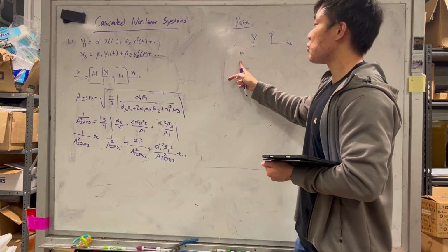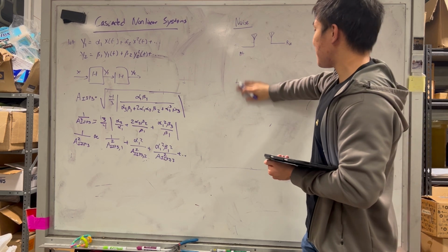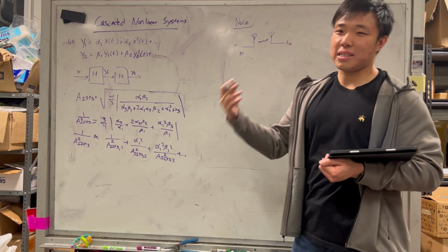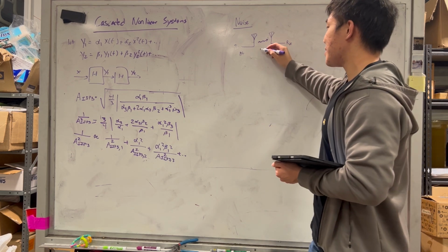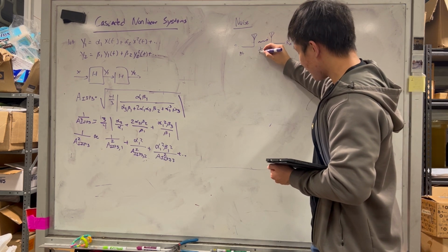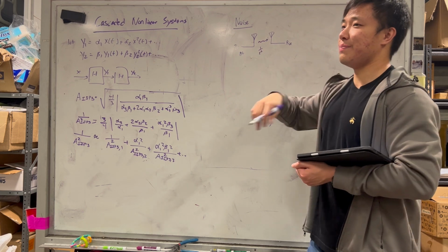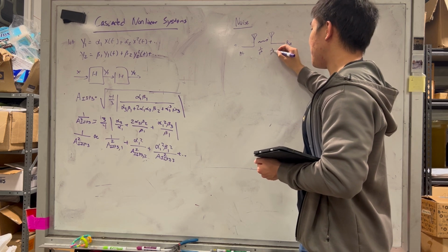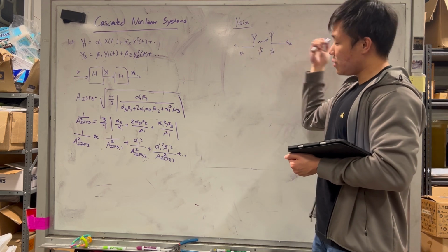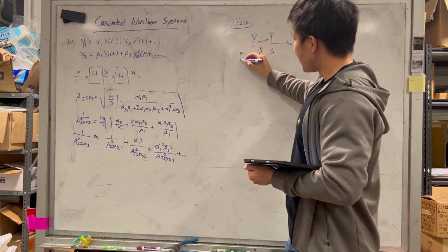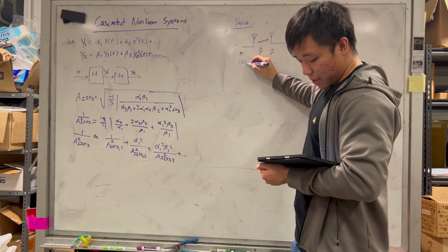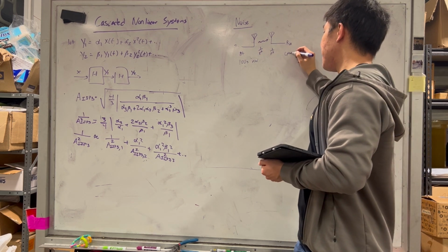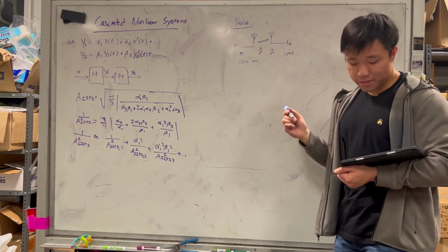And linearity is super, super critical because as it travels through this medium, in classes you'll learn that it gets attenuated by a term of 1 over r squared. But in reality, because of all the interferences of it bouncing everywhere, it's actually closer to 1 over r to the 4th. So you're actually seeing a huge amount of attenuation here. The power amplifier can maybe output something like hundreds of milliwatts. Once you get to here, you're looking at the regime of microwatts. You're looking at a very, very small signal here, right?